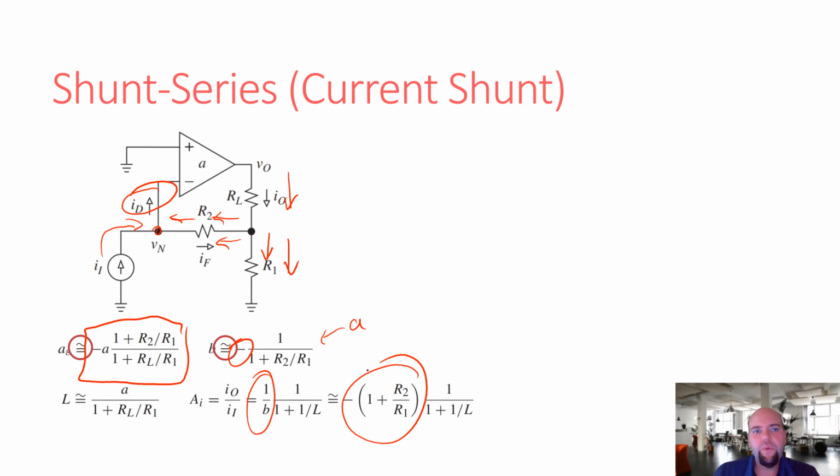So thinking about this as adding currents together to where the sum is driven to 0, we can think of I input flowing through here and this portion of I output that gets divided across R2 also flowing into there and summing to 0. So that's maybe, taking another stab at this, probably the best way to describe what's happening in this circuit.